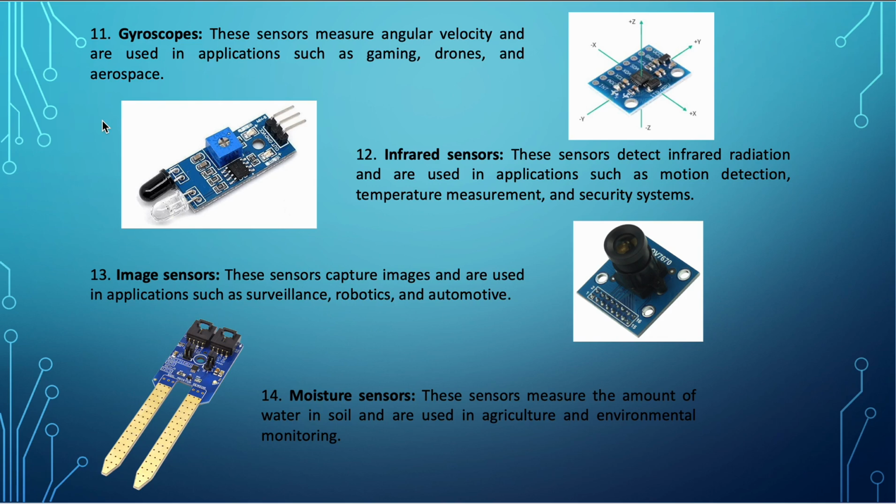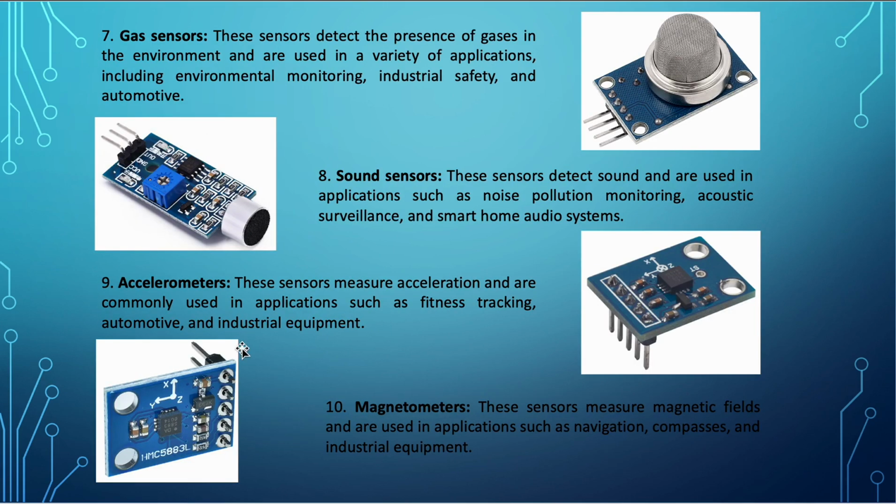So in that situation, drones should know which side is up and which side is down, or otherwise they will not work properly. They need angular velocity, definitely. So drones would need gyroscopes. And something that drones would also have would definitely be an accelerometer.